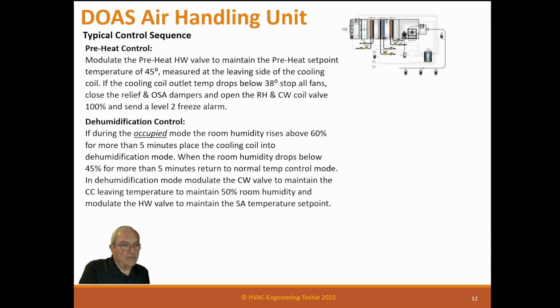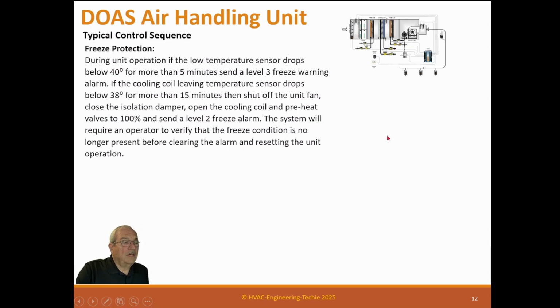So this is a standard dehumidification sequence that we would do, in which we just drop the cooling coil to wring the moisture out, and then take the heating coil to reheat the space. Now, you can always tell if an air handler can dehumidify if the heating coil is downstream of the cooling coil. If the heating coil is only upstream, then you cannot do a reset. And normally, if you have VAV boxes down there with a heat, which this one would never have, but if you have a regular building, you can't normally use those because there's not enough heat. You need more heat. So normally, a heating coil downstream of the cooling coil is a critical requirement to be able to do dehumidification.